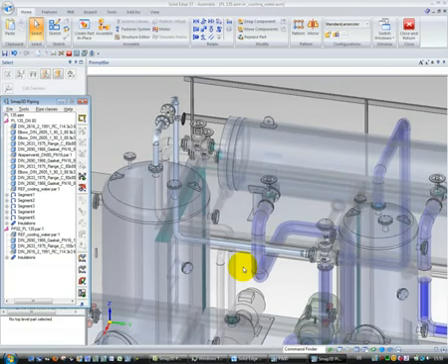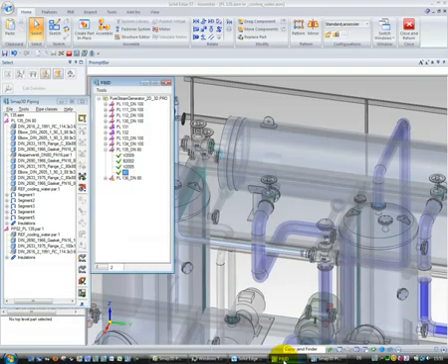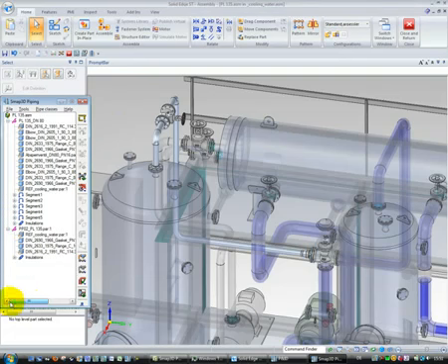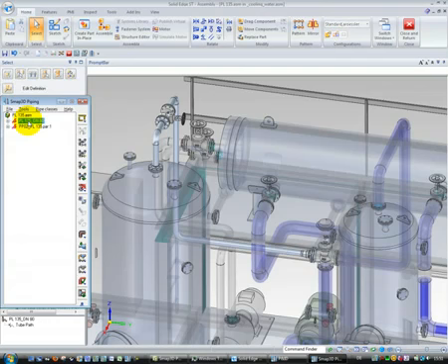If there are additional things required for this kind of pipeline which are not delivered from P&ID, for example insulation or similar things, then we can do this without the P&ID connection, because like I explained at the beginning, this piping functionality can also be used without the connection, if this is allowed for the user and if this is requested.